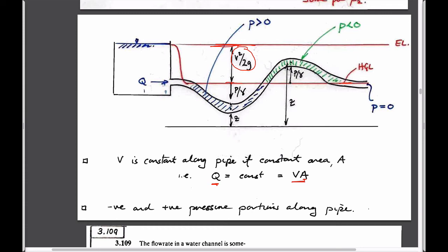And so by definition, the pressure acting at this point should be a positive pressure, and the elevation, if you put the height of the pipe above this, then this has to be negative. Or it should be lower than atmospheric, in this case.